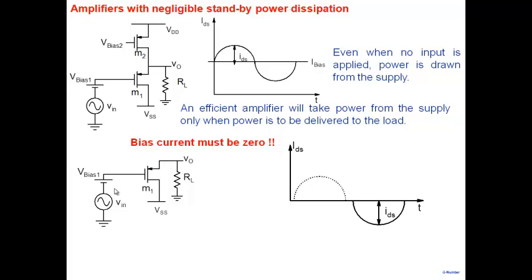So once it starts conducting, note that the relationship between V0 and Vin is V0 is equal to Vin plus Vt, right? Vin plus VGS basically here. So this voltage is VGS higher than Vin. So once the transistor starts conducting, V0 actually starts following Vin. Once it starts conducting, this becomes like a common drain stage here, and in a common drain stage, V0 follows Vin.